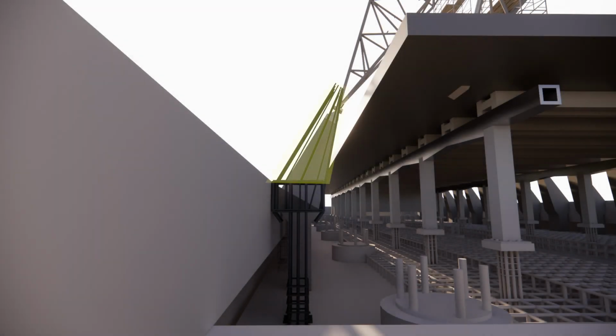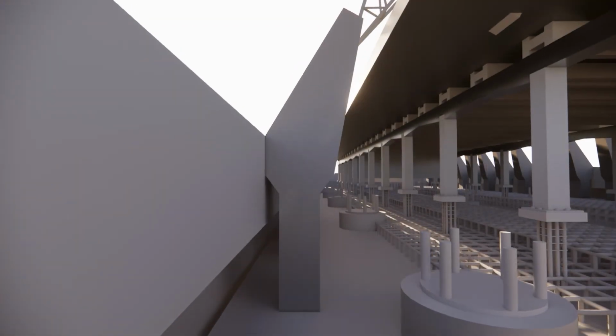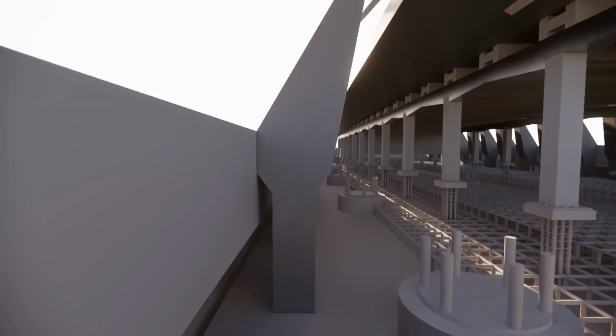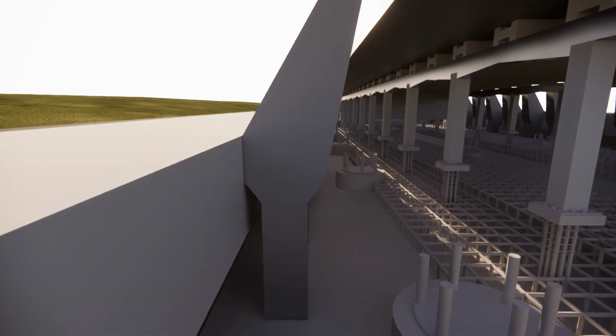The role of the support base is to transfer the load from the steel frame to the column. To do this, it's necessary to alter the direction of the force. For this reason, the support base is constructed diagonally. Similarly, the rebars rising from the RCC pier were placed diagonally, and through formwork, a support base made out of reinforced concrete was created.